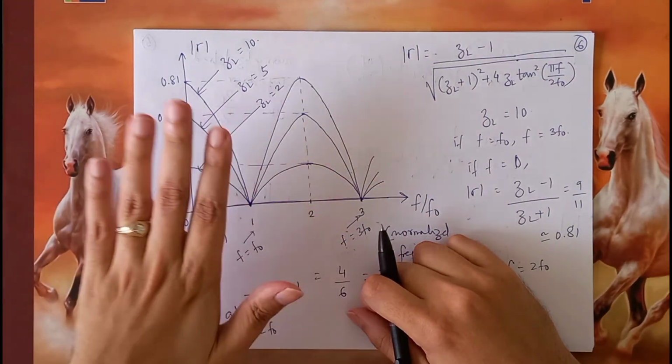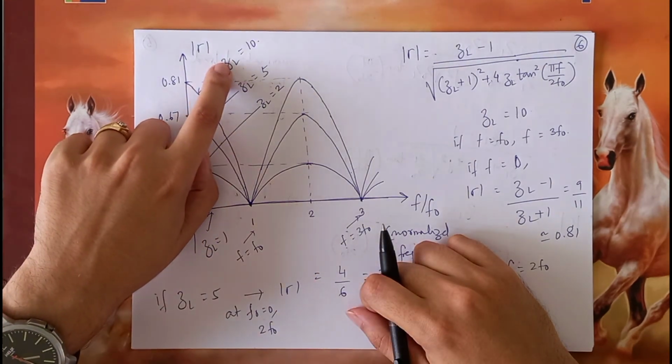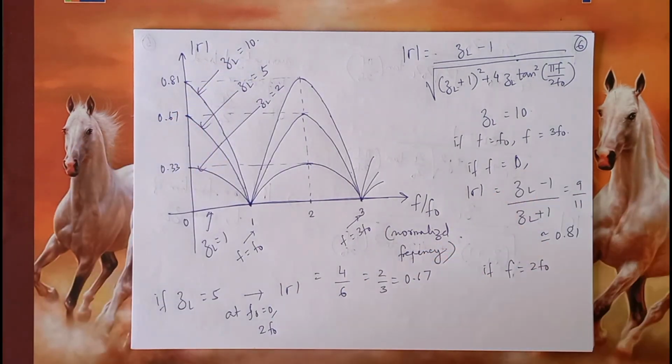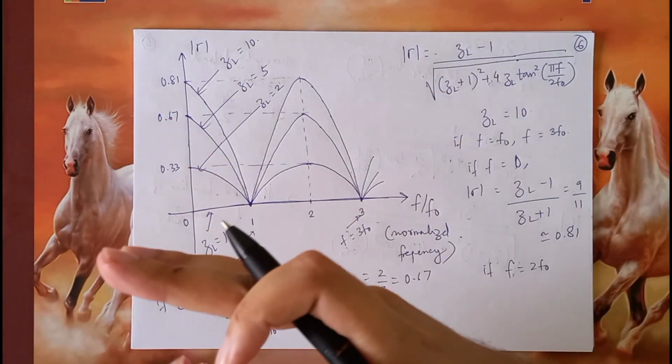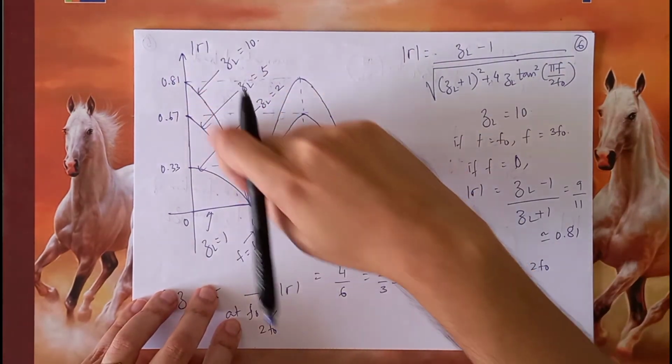So as a consequence of the closeness of impedance, the quarter wave transformer is able to provide a better matching. And as the value of normalized load impedance increases, that means that the line impedance and the load impedance are varying by a large amount. Then obviously they are more mismatched.